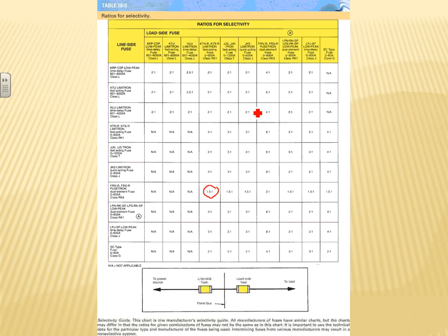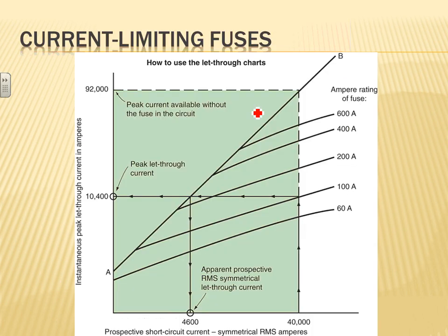Is that building code or NEC? In fact, NEC says if it's emergency, no? Okay, NEC. So that's for the fuses. It can be really hard to coordinate. So in many cases, the easy thing to do is to have separate feeders for each elevator directly from the main panel, instead of tapping one feeder to feed multiple.